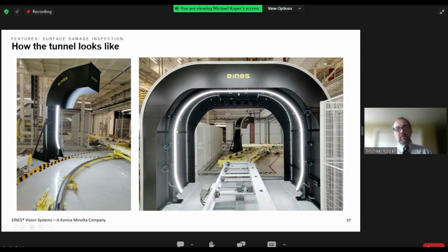So you can see there was a corner back here where our system's doing the tailgate inspection, and then as the vehicle comes through on these roller bed conveyors, we're able to do the defect detection of the balance of the vehicle once it enters our system. And remember, this is not stopping at any point in time. None of our systems are stop station. They're all in line while the vehicle is moving.